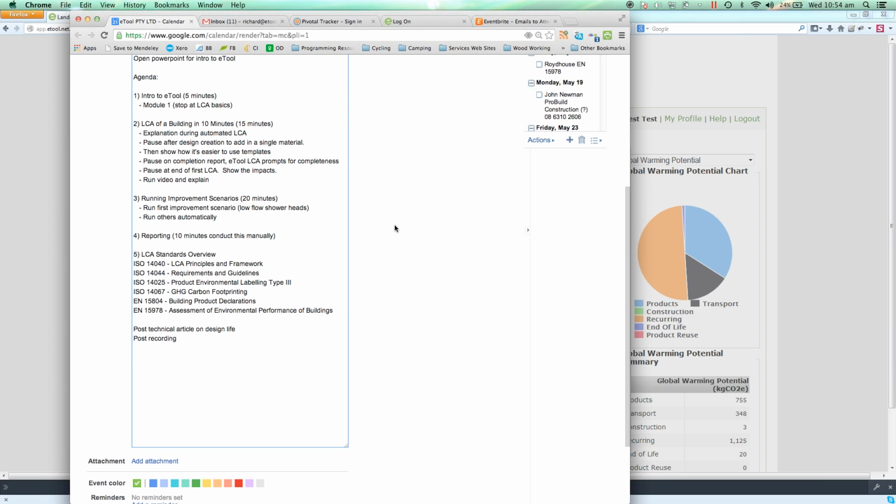Yep. That would be one of the things. Yeah. Because the other element to that would be how the thermal performance is going to change for those different buildings. So thermal mass. That's right. Thermal mass isn't as important for commercial buildings, but for residential buildings it becomes quite important, particularly for a region like Perth, which has such a good temperature range on an average day.